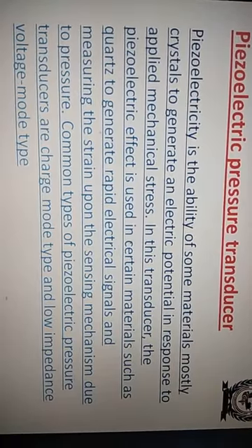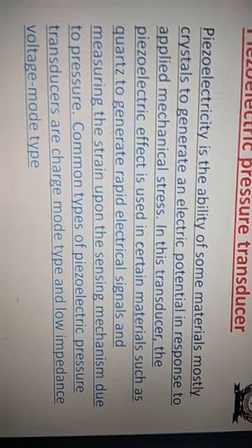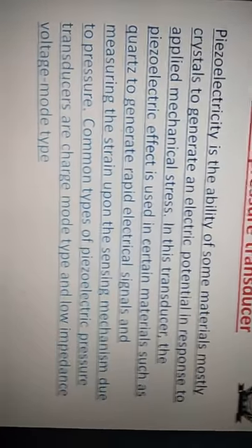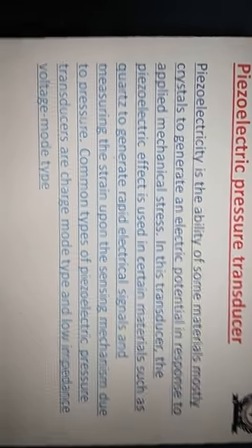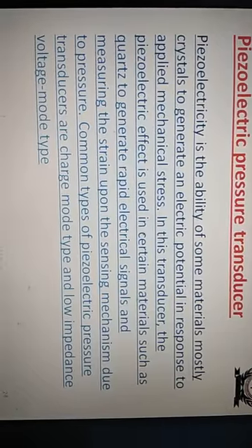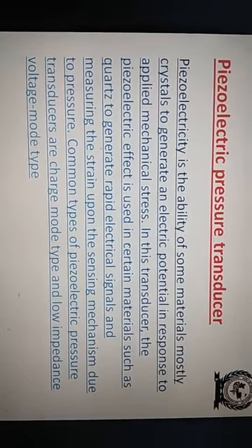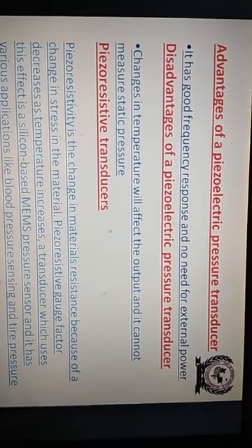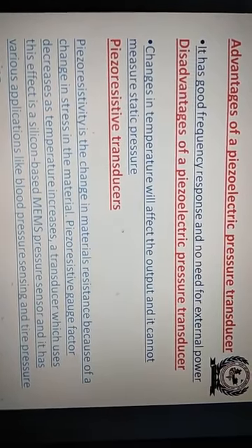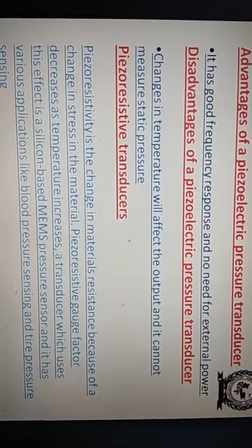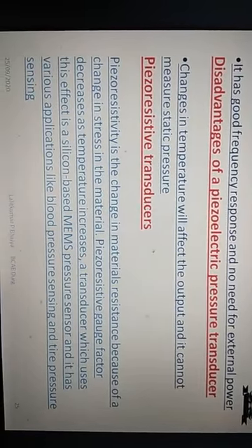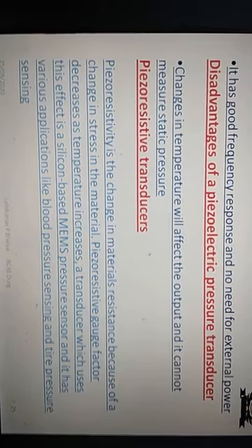Common types of piezoelectric pressure transducers are the charge mode type and the low impedance voltage mode type. These are the two types commonly used. It has a good frequency response and no need for external power because it is like a crystal. Its disadvantages are that changes in temperature will affect the output, and it cannot measure static pressure.